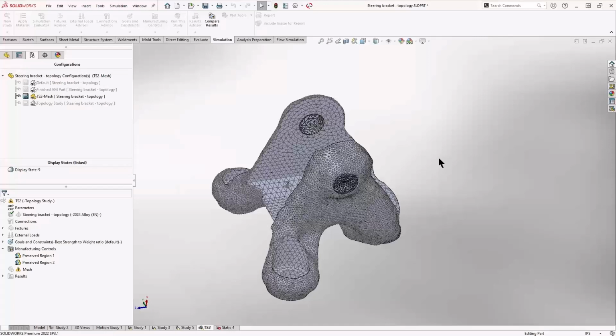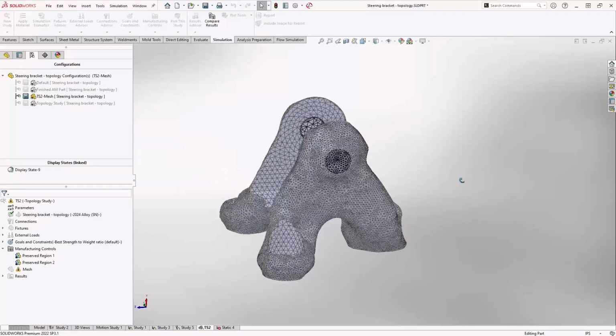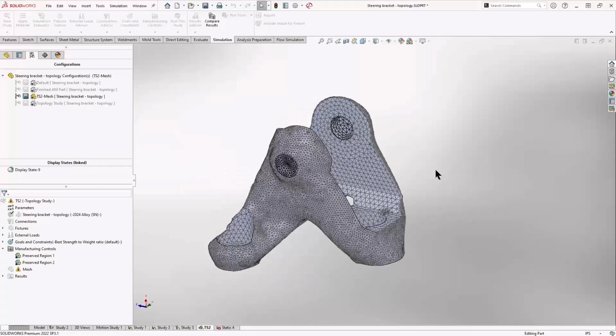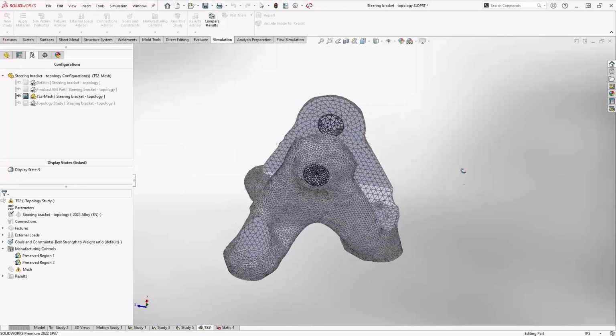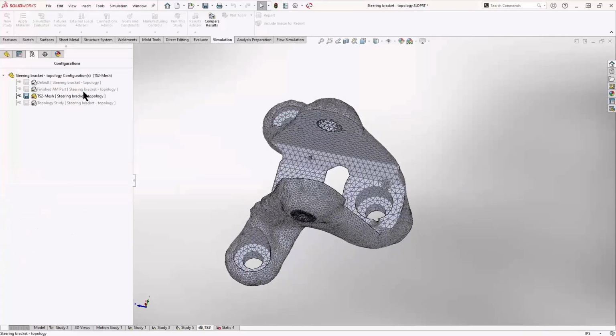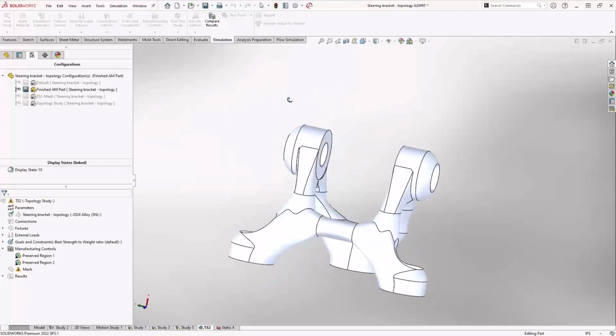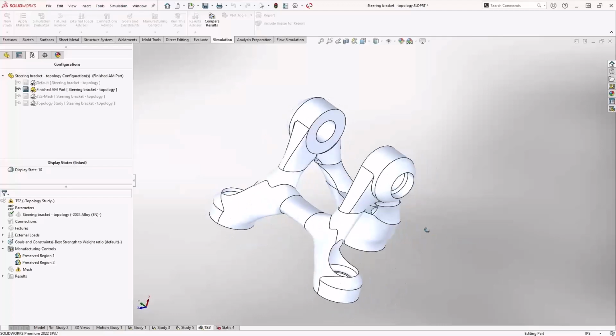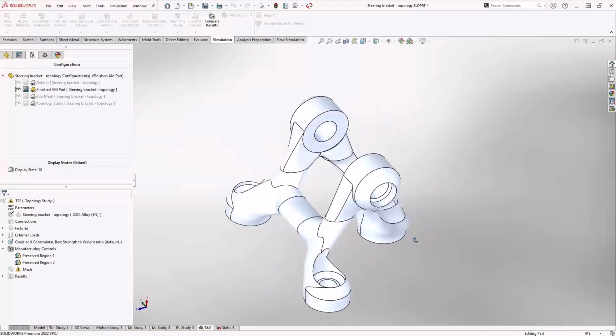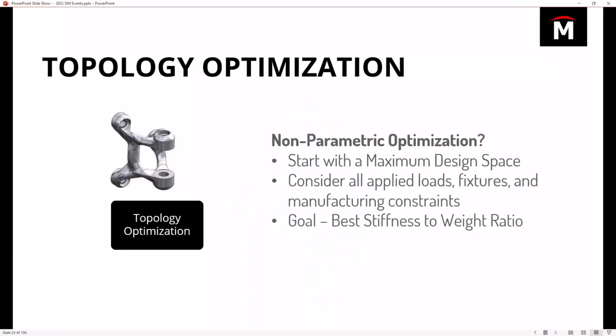So instead, if you are stuck, not with just being able to 3D print or cast in your application, I would say the other output it puts out is a material mass plot and stress plots, just like you saw earlier, which you can show in the regular modeling environment and use like a template the same way I use to cut my material out of the last part. If you do something like that and you really apply yourself and you get into SOLIDWORKS surfacing or X shape, maybe you come up with something that looks like this. Maybe still not the easiest in the world to manufacture, but looks a lot smoother. And we got these ideas from the results of that topology study.